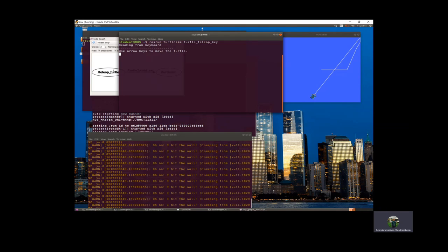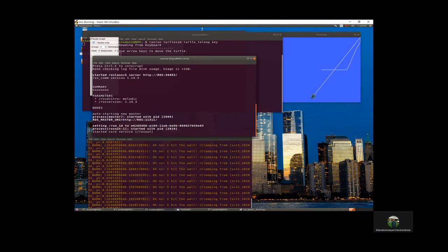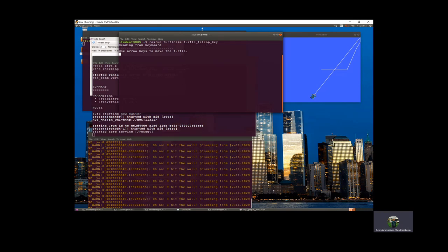Now to run that, here I'm actually having the master node. So let's say for now, I'm just going to exit this. So I can use rostopic list. When I use rostopic list, it's going to show me all possible topics that exist in the system. So here you have rosout, aggregate, statistics, command velocity, and so on.